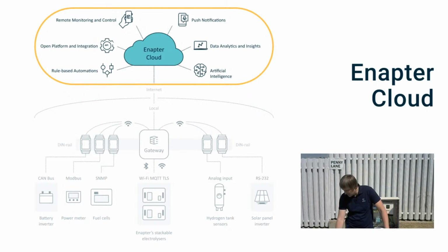Okay, one more question. As I mentioned, for advanced logic, we require the gateway. In this case, the integrator can use the rule-based engine on the gateway to set up very complex and nested logic. In our case, for this EMP RS-232 module, the logic is very simple and user-oriented. Therefore, this part is running directly on the module. You don't need a gateway for this.